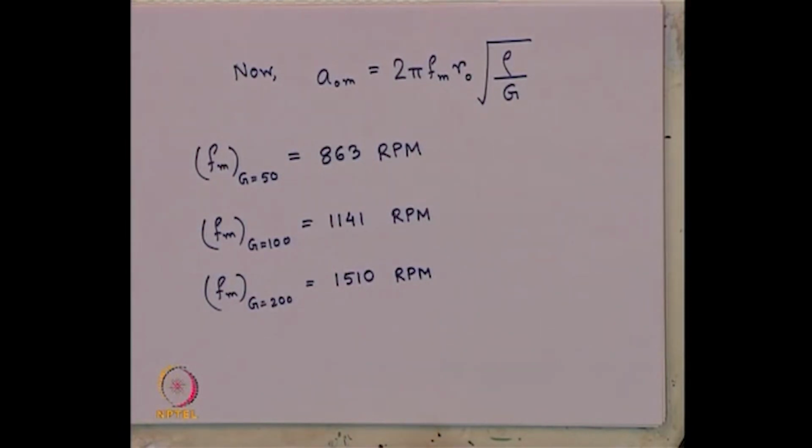So, remember, when the same foundation we are planning to operate at operating frequency of 1500 RPM, for this third type of soil, usage of it is ruled out, because the operating frequency then will be very close to the resonant frequency, which should be avoided as per the design criteria.